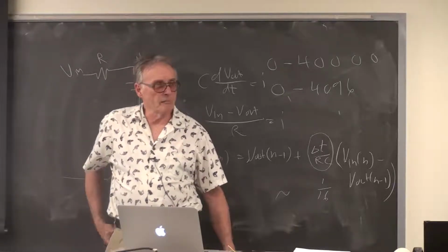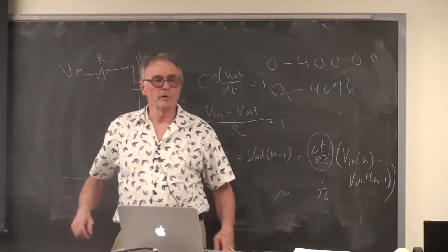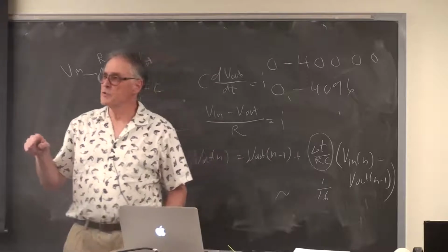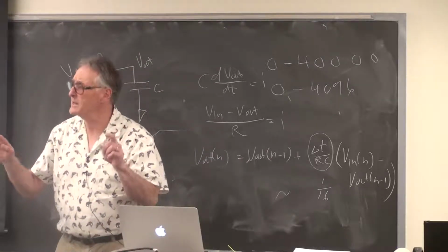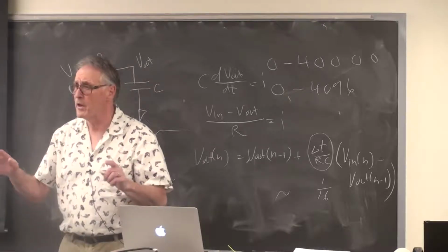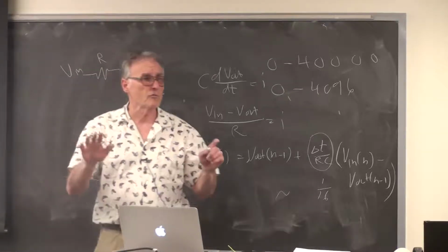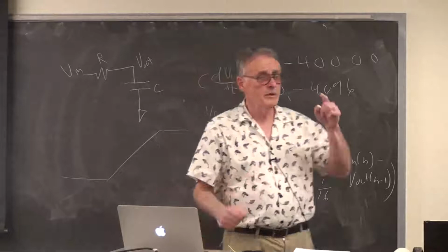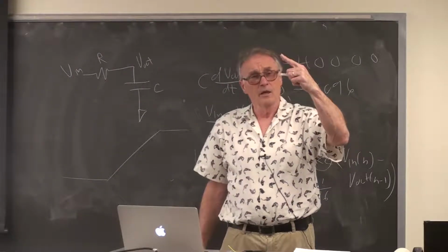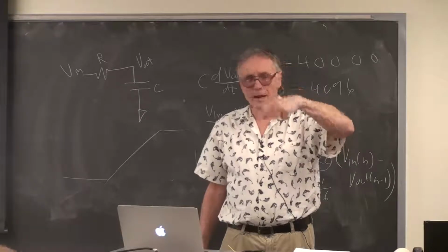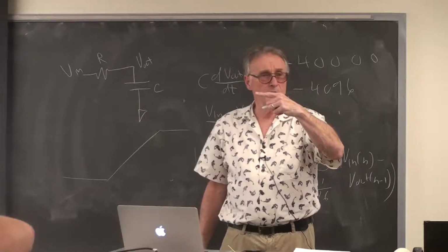At boot time, when you press reset, the system should come up with the best KP, KI, and KD set that you could come up with, and the system should run the control algorithm -90 to 0 to +30 to 0 to -30 back to 0.